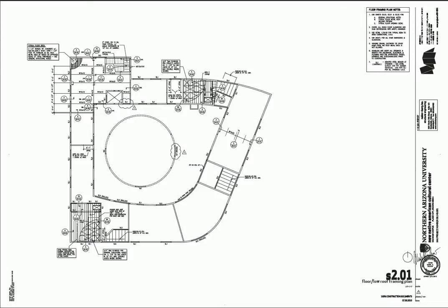I'm going to go to the next page here. You can see this says framing plan. So framing indicates that it's structural. So I might concentrate a lot down here on the titles of the pages. You can see right below here that these were issued for 100% construction documents, so I expect them to be complete. This has floor and low roof, so I'm looking at this saying, okay, some of these spaces look like they're open, and some of them look like they might be floors, and some might be roofs. So I'm not quite sure what's going on.